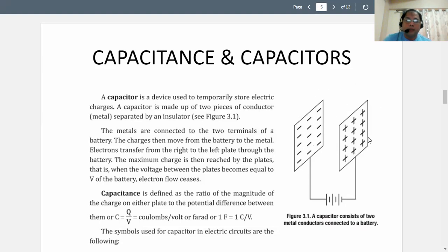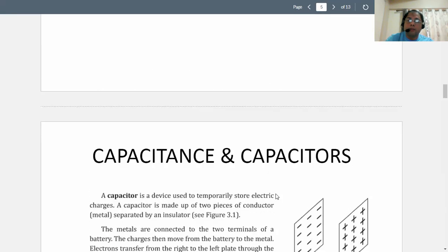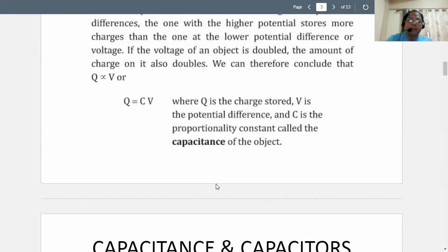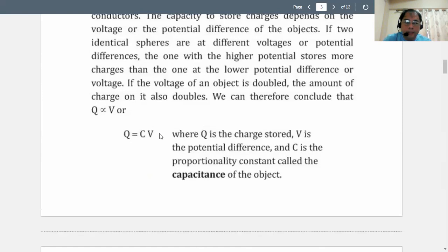That is because we place some voltage in our plate, so the plate becomes charged eventually. So the charge Q is a result of putting a voltage in between. And then there's a factor, the constant of proportionality, as you add a voltage to the plate, and that's what they call the capacitance value. So capacitance times voltage will now give you your charge Q.